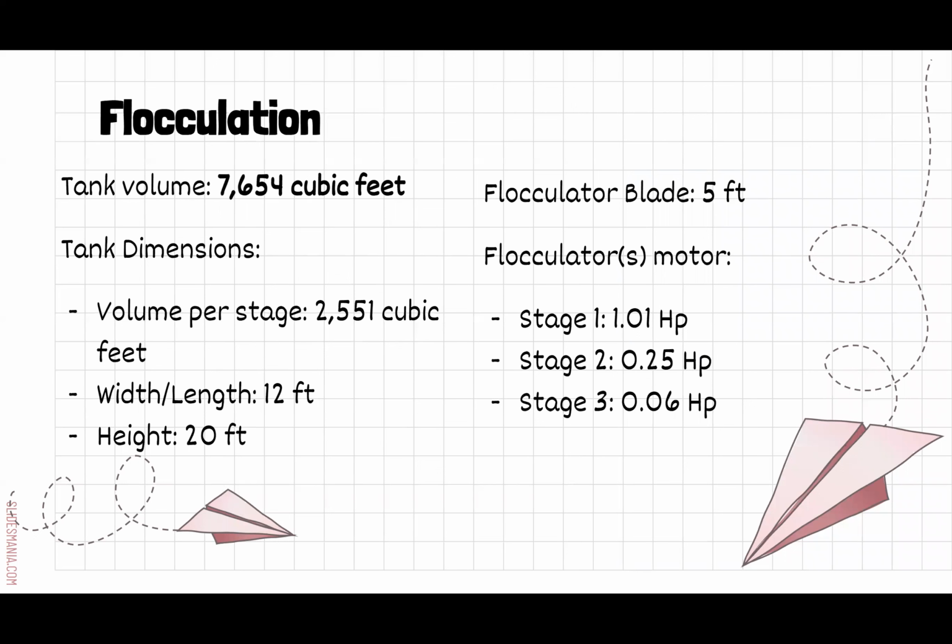Okay, thank you, Jamie. So flocculation is a process by which a chemical coagulant is added to the water and acts as a bonding between particles, which helps create larger aggregates, which will make it easier to separate in the later treatment process. For our flocculation system design, we had to design for 11 MGD flow, which will consist of 4 tanks, each consisting of 3 stages. Our detention time of the vertical shafts will have a design criterion of 30 minutes.